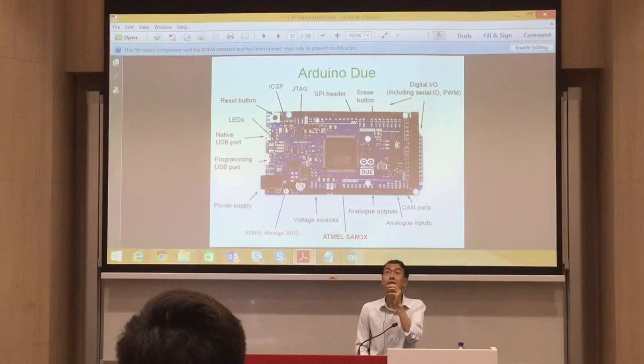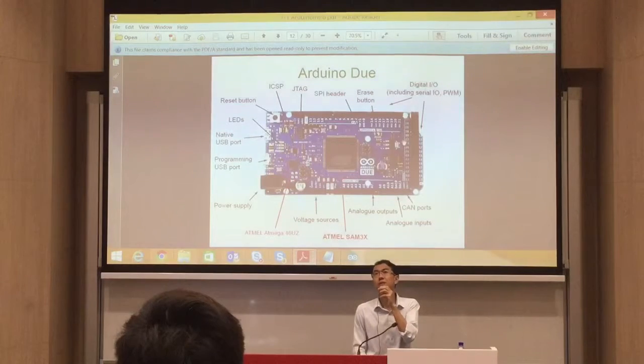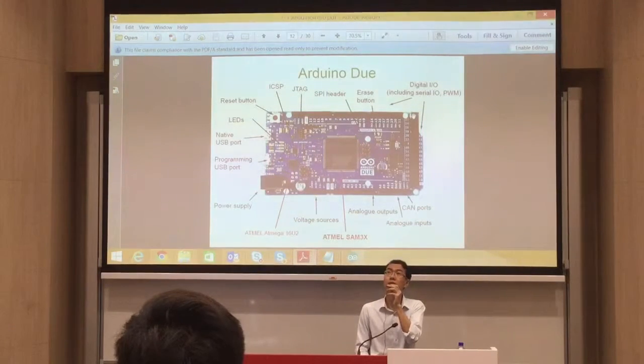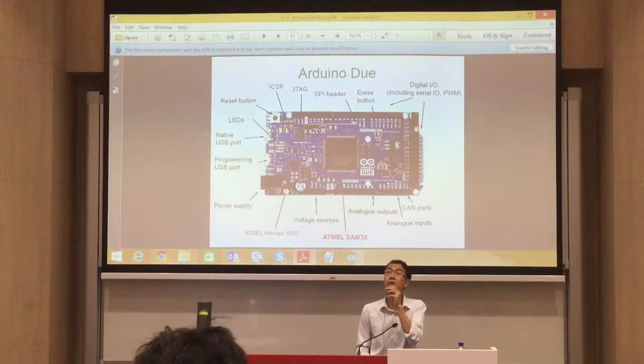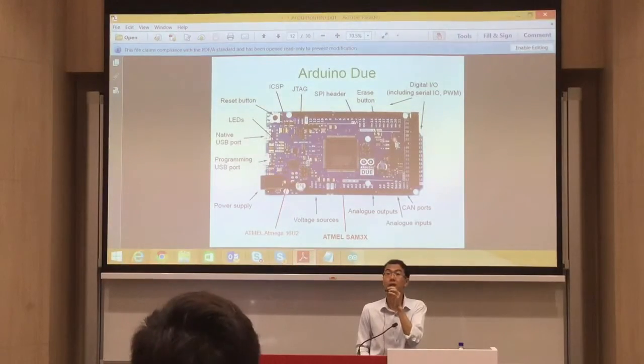We also discussed the ports here. These are the digital I/O. These two rows are also digital I/O ports, and here are the analog I/O ports. We have about 50 digital I/Os you can use, and you can check the exact number. In the example just now we used pin 6 and pin 8, somewhere here. Of course, you can use, for example, pin 20 or pin 30. They are also available.